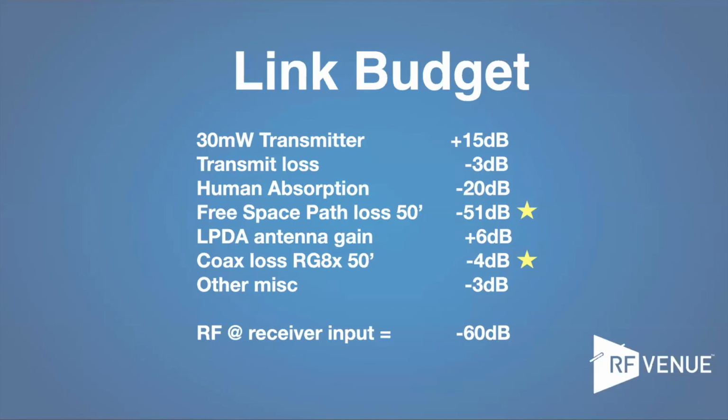Yep. I mean, this figure goes up to LMR 600. That's some serious stuff. By the time you get to that level, then we can start looking at running RF over fiber, which is easy. 100 meters of fiber weighs a pound. I can hold it up with my finger. 100 meters of LMR 600 or RG8 is time to go get a forklift. So especially if you want to pull that through a ceiling or something, that's a tough job.